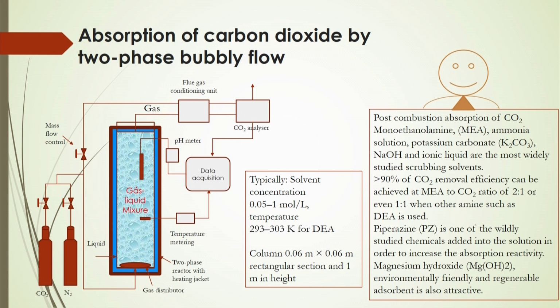Suppose you consider the concentration difference from the interface to its equilibrium concentration of that carbon dioxide molecule, then you will get the individual mass transfer coefficient for the gas, and also for the liquid there will be an increase of concentration of carbon dioxide from its beginning to the final equilibrium stage. So, there will be a concentration gradient.